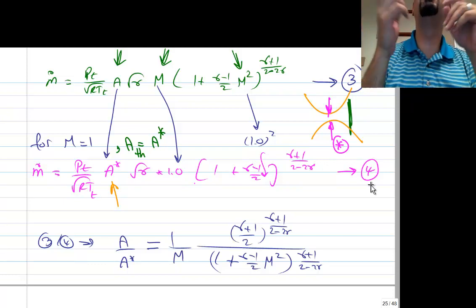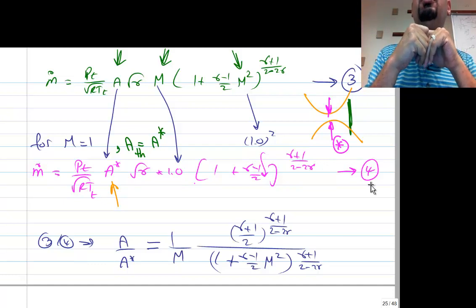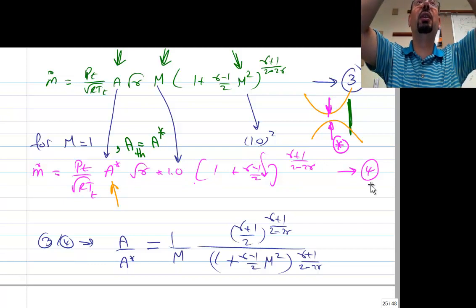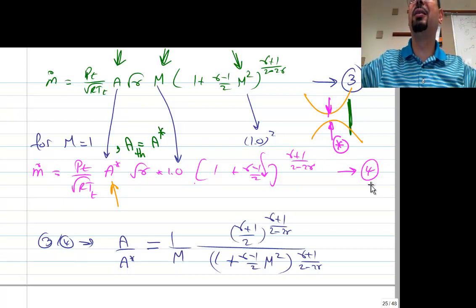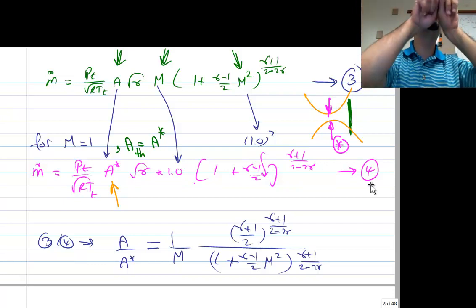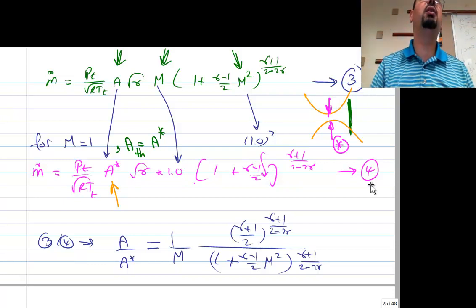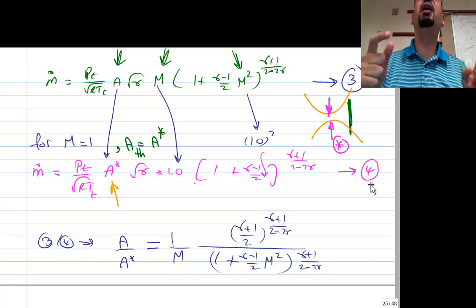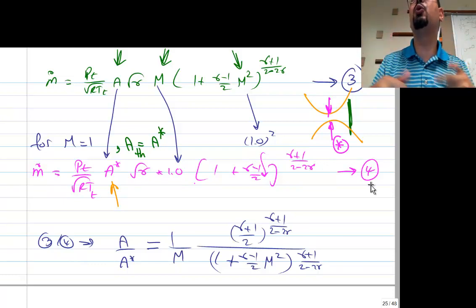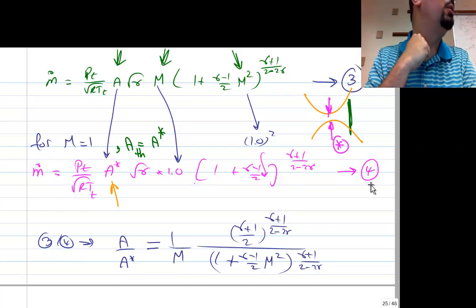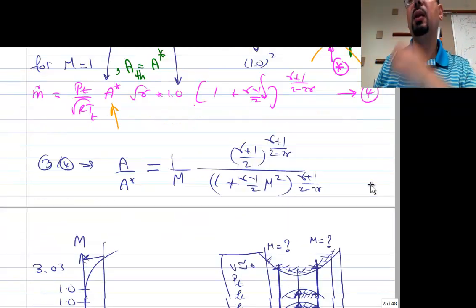So now you can go back to the Saturn rocket engine and measure area exit over area star. Notice that the area is not the diameter, the area is diameter squared. So from the picture you can measure the exit diameter and the throat diameter, get the ratio, say 5 times bigger, and then the area ratio will be squared, so 25. Then you can back it up and figure out what exit Mach number they had. Okay? Very good.